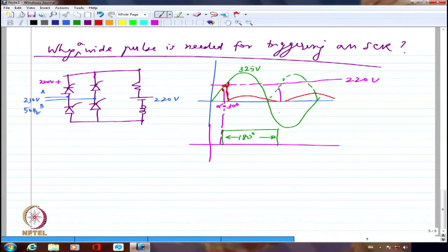So we generally say there are two modes of battery charging. One will be constant current charging, which is initially done when the voltage is very small for the battery, minimum value of voltage, minimum charge condition. Constant voltage charging when it is almost full. So there are two modes of charging we normally adopt in battery: constant current charging and constant voltage charging. Right? So there is no guarantee that it will be continuous current. It heavily depends upon the state of charge of the battery. What is the charge that is already accumulated in the battery?